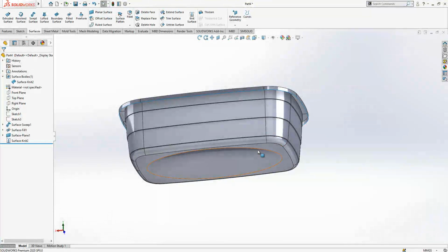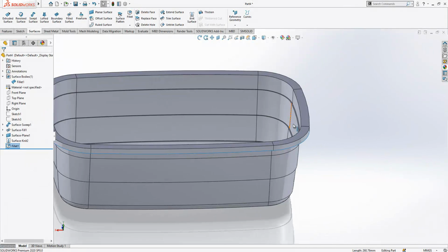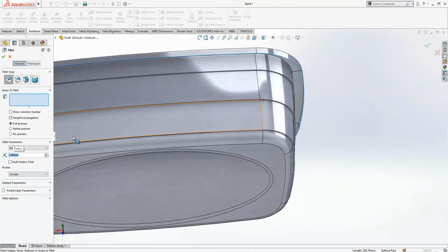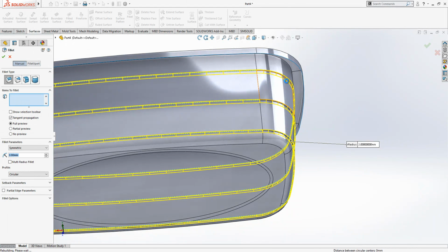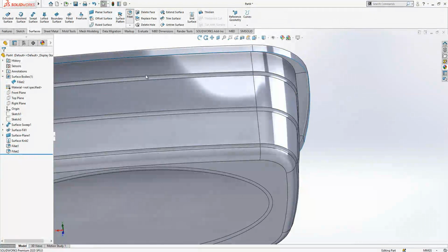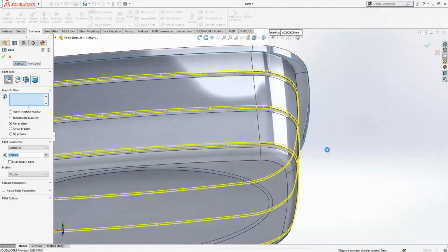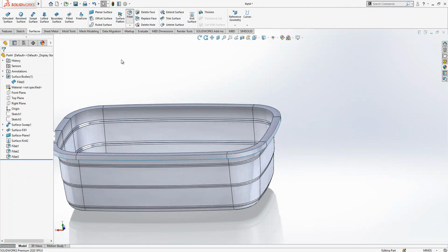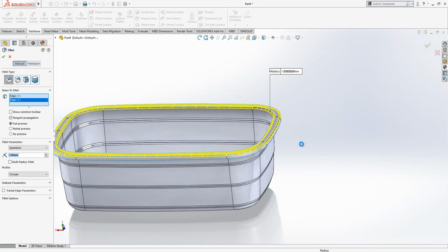Now we can start to give some radiuses. Fillet here at 10, looking all right, and we have here radius 2s. 2 first here, second and third here, 3x, and fillet again 2, and then we are going to give here as well. This is the real model, guys, by the way. I'm not creating something imaginary. And 2 times 1 here.